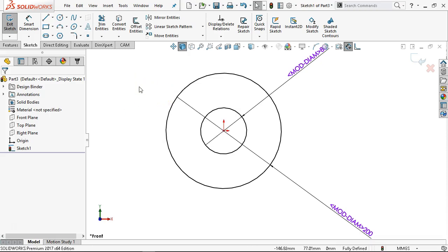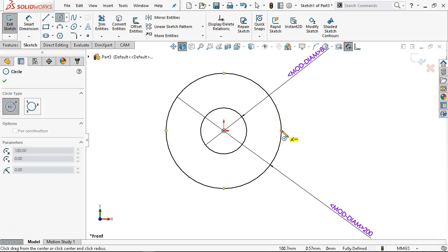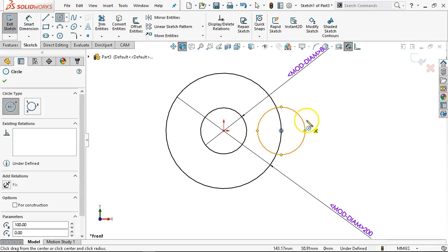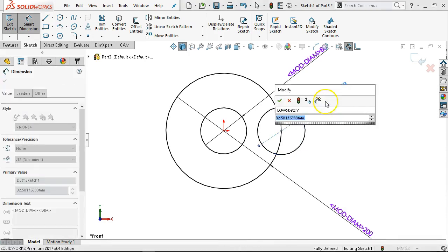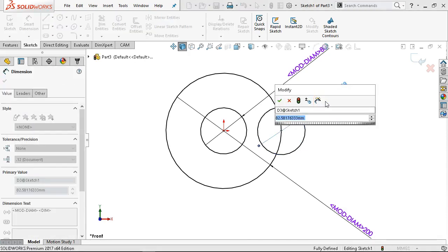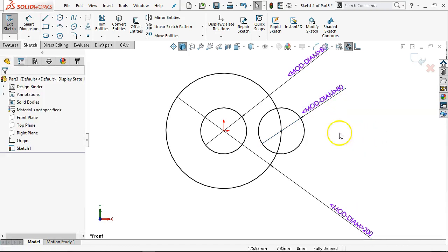the selection. All right, so going into the circle, I'm looking for its quadrant. I'm looking for those 2 little yellow boxes. And then we'll go into the dimension. That was a radius of 40, so 80. And then do I want to draw 4 of these, or do I want to pattern?